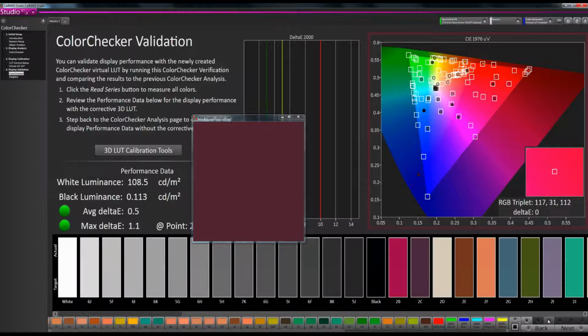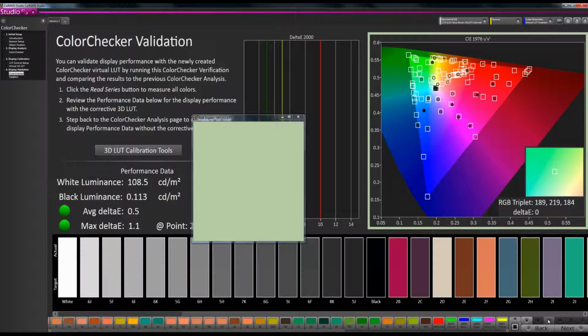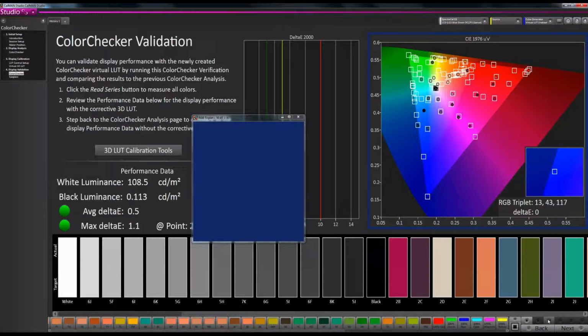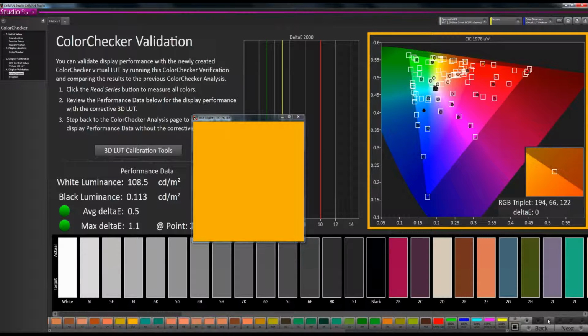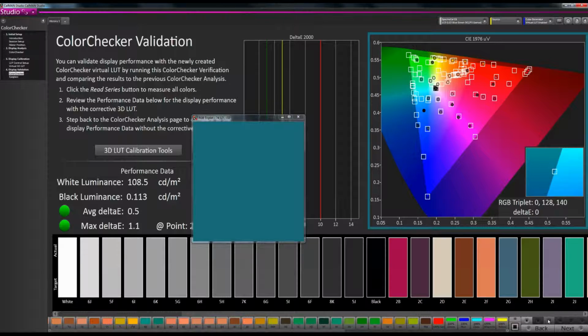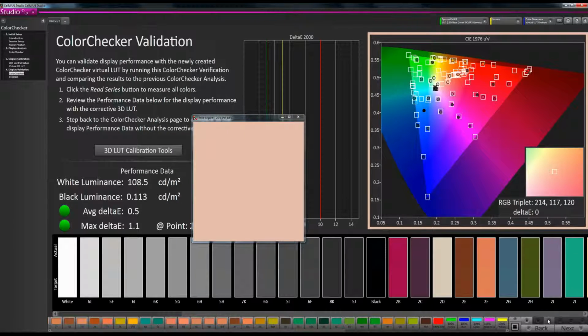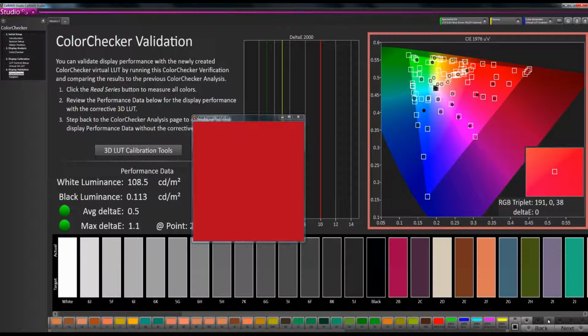But now we have digital displays, and they can have whatever gamma you program into them. So the ITU came up with this specification BT1886, which also takes into account the actual black level of the display instead of just a theoretical 0 black. So then your content will look similar on displays that have different black levels if you target BT1886 as your gamma. Okay, that makes a lot of sense.